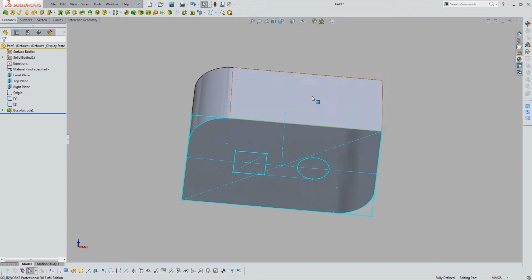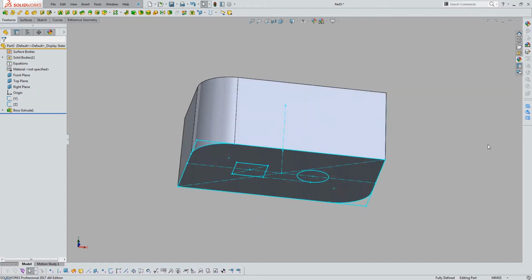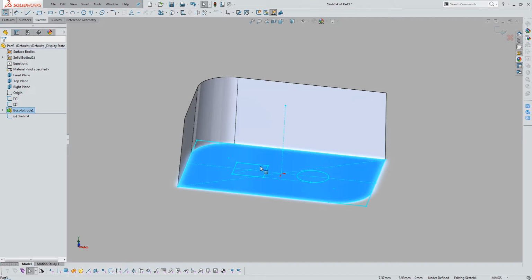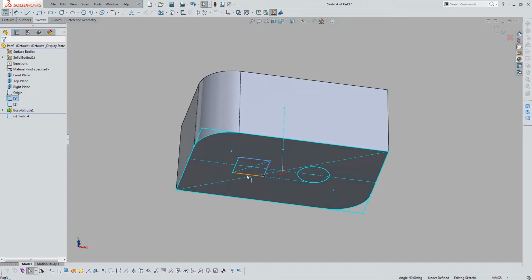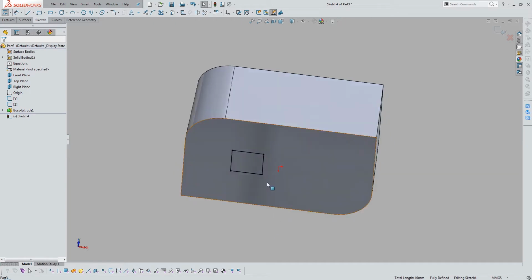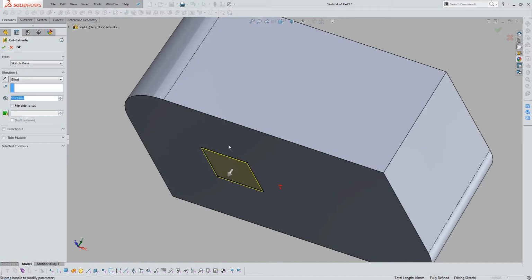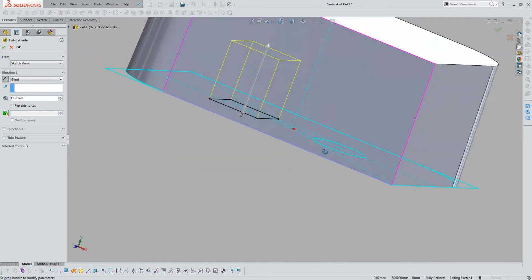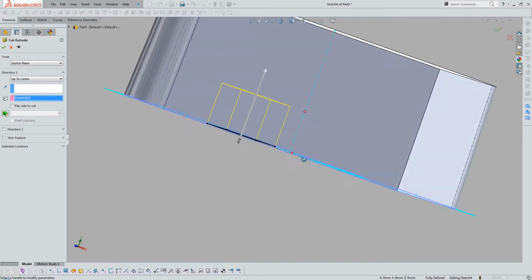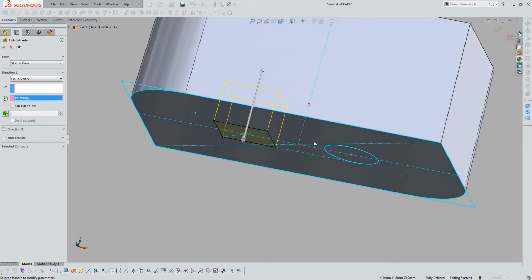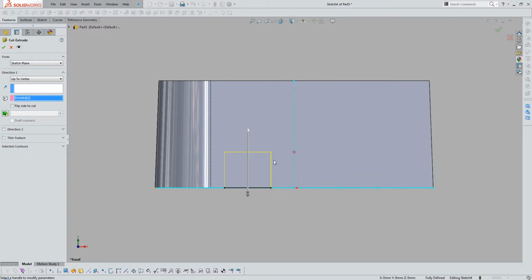So I will put this square hole up from the bottom. So I'll start my sketch on the top plane. I'll borrow these lines from the master sketch. And now I'll do an extrude cut. How far? Well, I've got a sketch for that. So I'll select this point that I specifically created for this feature. And now, if I view this from the side, you can see those lines are vertical as well.